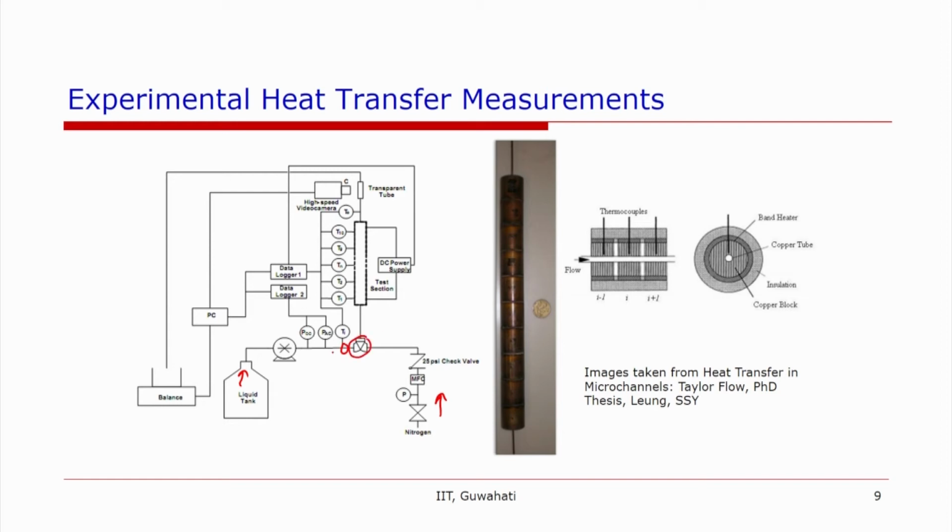Then they come into a mixing section, and the fluid moves along the test section, and the wall temperature is being measured at different sections. The wall is being heated by a power supply. This is a test section that was used by Ms. Leong in her experiments at the University of Sydney, and then the outlet temperature is measured.